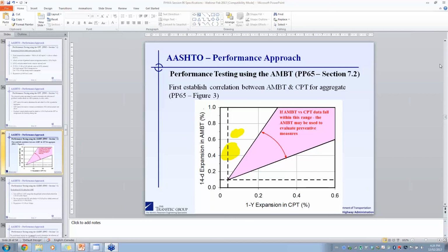It is true that you don't get as much, or very little, exudation activity around alkali carbonate reactive cracks, or even none, but you can also get alkali silica reactive aggregates that give you little gel exudation. So in my opinion, and I'll ask Benoit to give his opinion in a second, if you've got map cracking on concrete and you want to determine whether it is ASR or ACR, you have to take a core. Yeah, this is certainly the safest way for sure. I agree with you, Mike.